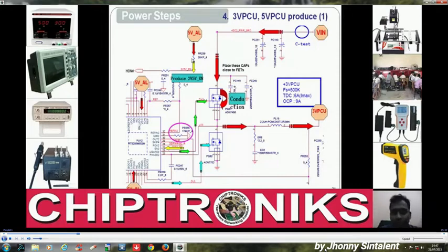Okay, so what we have studied till now: the V in is going to the IC, V in through a resistance divider is going to the enable LDO pin, it generates LDO which is labeled as 5v_al, and that 5v_al powers VCC and PVCC. VCC is for supplying the internal logic of the 3.3/5 volt regulator IC, whereas the PVCC is supplied to the internal gate drive circuit, which will generate the gate drive for the lower MOSFET. Okay, and this 5v_al is also generating the enable signal.